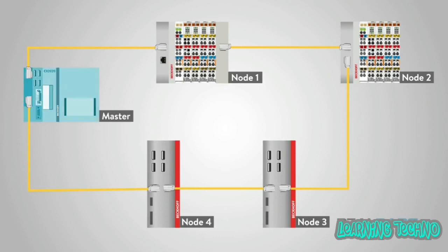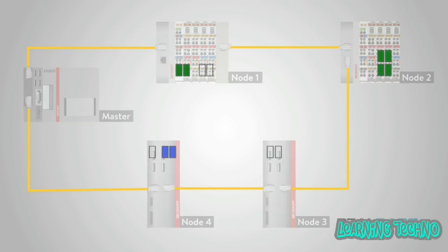With EtherCAT, the master sends data, possibly only a single frame for the entire node network, that will pass through each node. The master is the boss, and is the only node allowed to send a frame. The frame is then forwarded downstream by each node in the network. This approach helps to assure real-time operation and avoids delays.